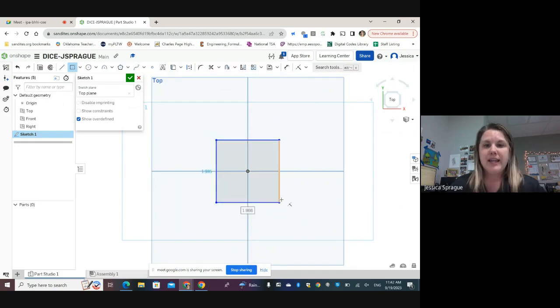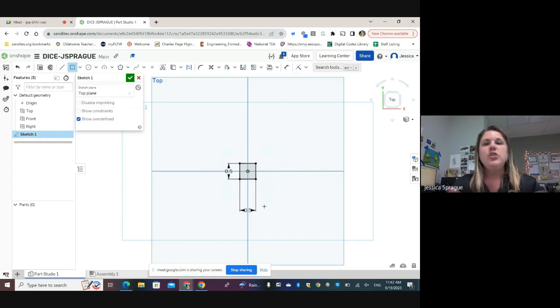After your second click, when the sketch light blue turns to dark blue and you've anchored your shape and you've got these text boxes that pop up around the numbers, that's when it's active and able to adjust the dimension. Do not click inside the text box. If you click inside the text box, it will start generating an additional shape. What you want to do from this point is just go ahead and start typing your dimensions. 0.5, hit enter, 0.5, hit enter. And then you'll be set with the shape in the appropriate dimensions that you want.